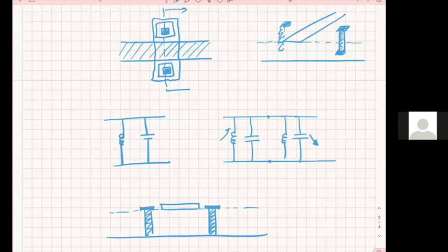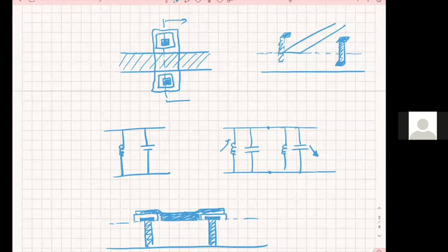I'm trying to show you how you're gonna fabricate it, and then you put a dielectric, and then a metal. So now I have my capacitor here. That's how people will do it, okay? So it's a shunt capacitor.